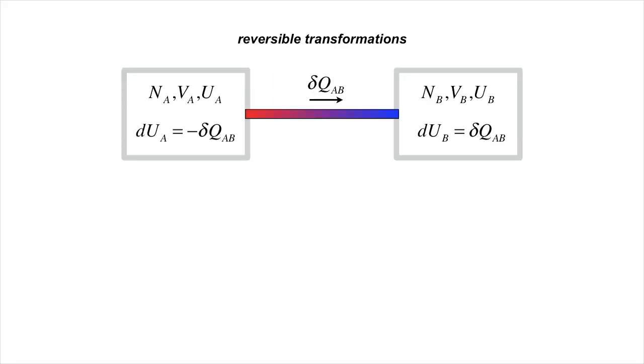A second, perhaps more general way to think about entropy generation is macroscopically, based on the thermodynamic definition of temperature as du/ds at constant V. Specifically, recall our previous thought experiment involving heat flow between two systems A and B. We found that if the temperature of both systems is the same, no entropy is generated by flow of a differential quantity of heat, dQ_AB, from system A to system B.